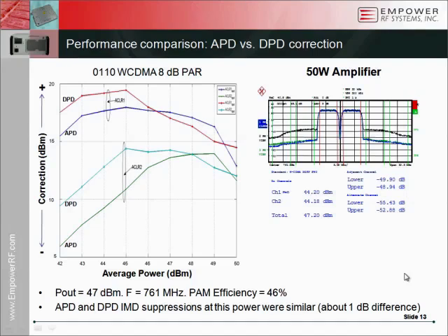This chart you're talking about? Yes. This is ACLR1. This is the DPD correction. This is increasing correction. And this is ACLR2. ACLR2 in this chart is lower than the amount of correction because of the noise floor of the measurement system. Okay? So that's all it's showing here.